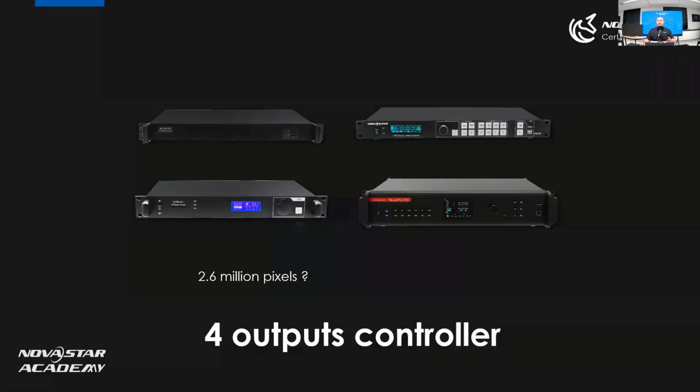why we have four outputs, but on our specification, the loading capacity is not 2.6 million pixels. This is very important, because every time the client will ask me, so hey Angus, why do you have four outputs, but the loading capacity on your specification is not 2.6, it's just 2.3 million pixels. I'm sure some of you also wonder about the answer to this question. To be honest, this limitation does not come from the output. This limitation comes from the input.